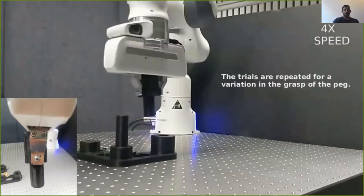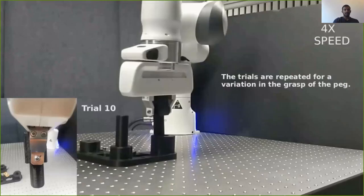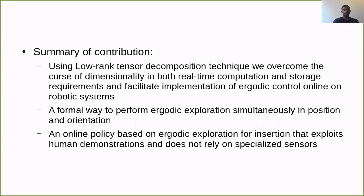In the paper, we highlight other properties of ergodic control that make it particularly suitable for insertion tasks. Finally, we summarize the contribution. We use the low-rank tensor train decomposition technique to overcome the curse of dimensionality for closed-loop ergodic control using the spectral multiscale coverage algorithm. We provide a formal way to perform ergodic exploration simultaneously in position and orientation using Riemannian geometry. We proposed and demonstrated the benefits of ergodic exploration for insertion tasks.